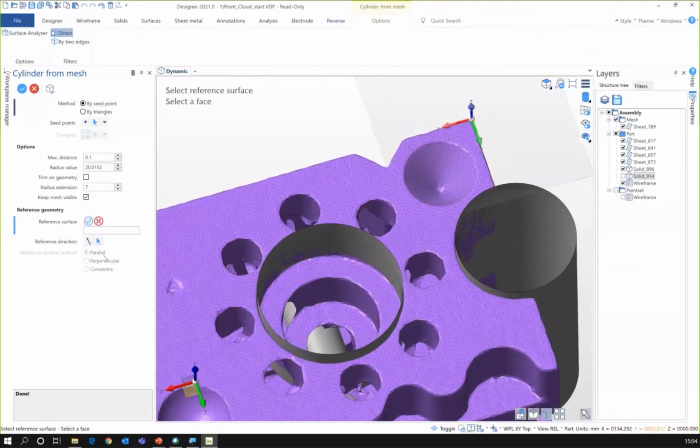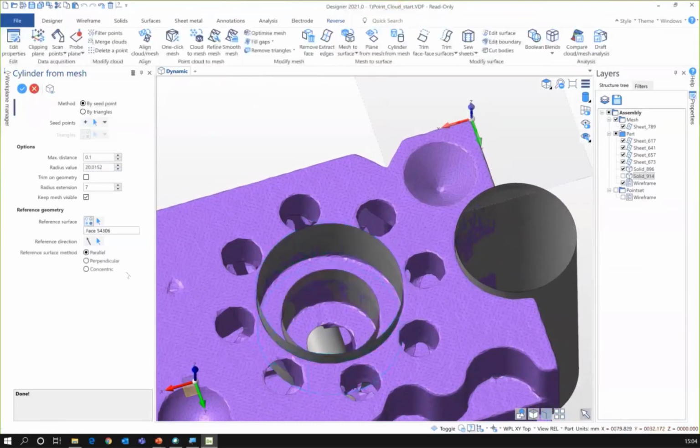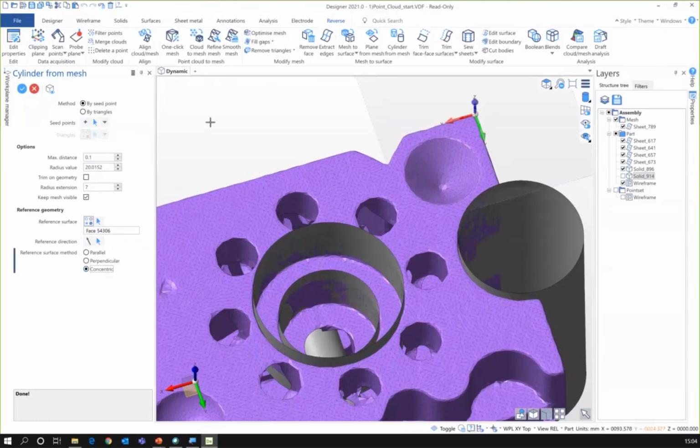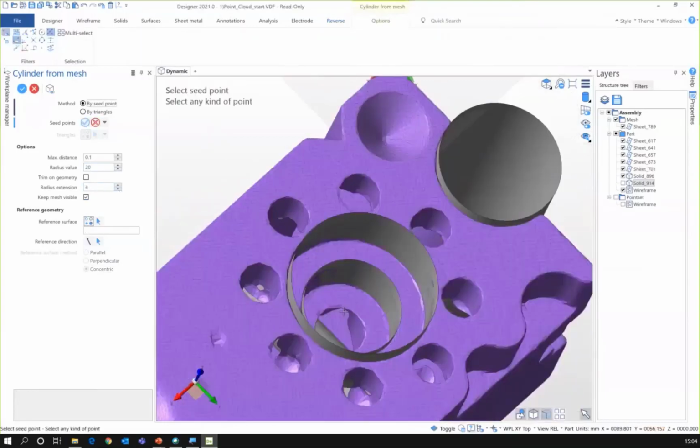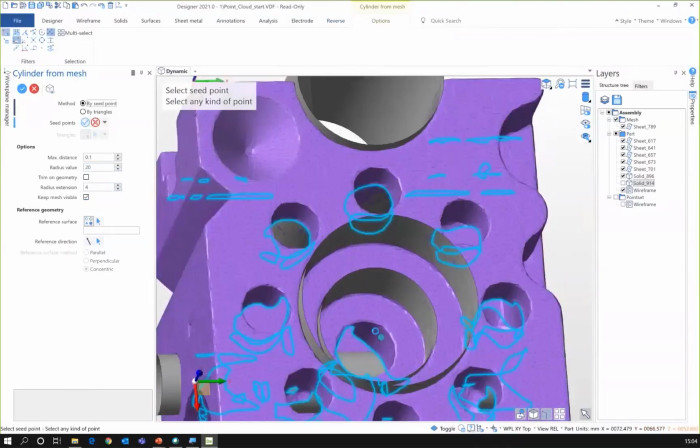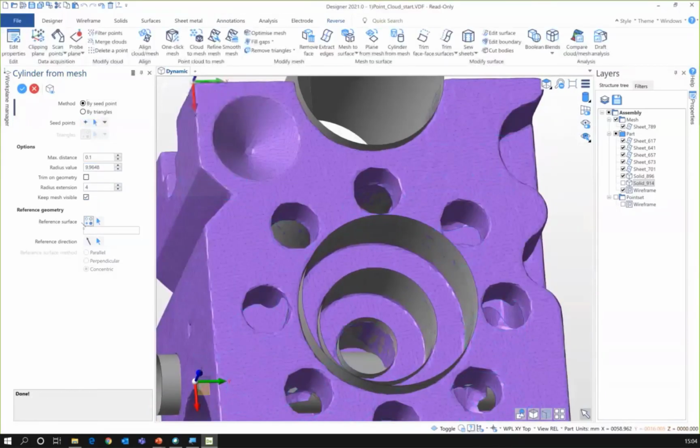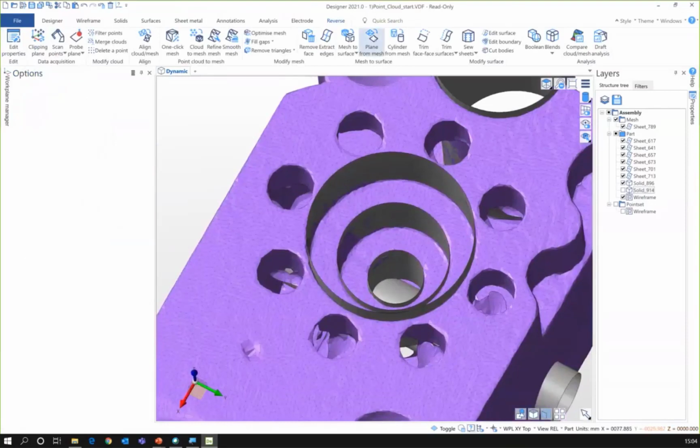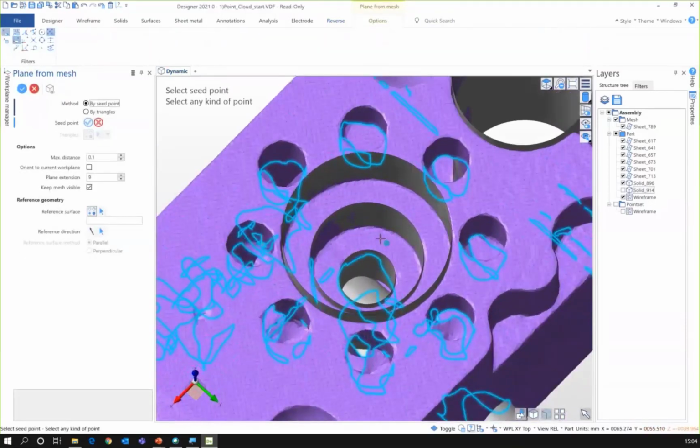And this time, okay, we want to use the concentric. So we can say concentric to this guy, and it means they've all got the same center point. Again, we can set the radius to be something more sensible. So 20 makes sense. To be honest, I don't need my radius extension to be that big. And apply that. And then down here where we've got the least data, we can come in and say concentric to that guy. Make sure we've got the nice round value. And we've got it.